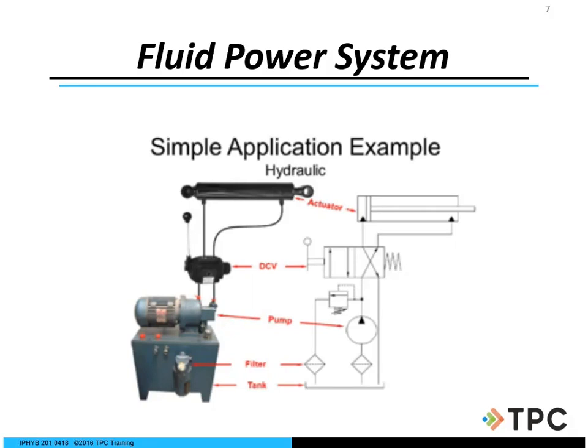Okay, so if we don't have a proper alignment between our motor shaft and our pump shaft, guess what wears out? Our motors and pumps and the bearings. Bearings are critically important. And so if you don't have that proper alignment or the proper shimming of the motor and the pump, so you can have that proper alignment, bearings will fail very quickly.